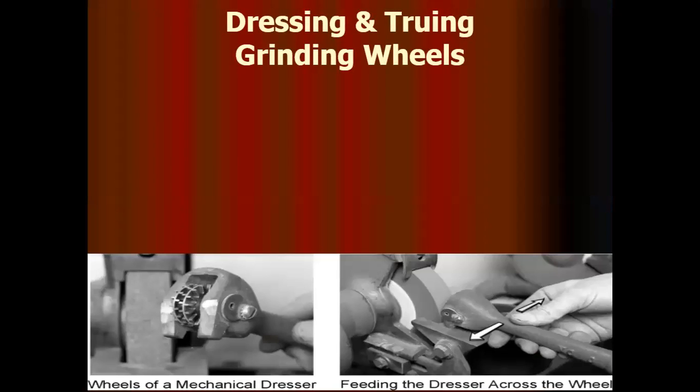Sometimes those wheels, they get a little out of true. Students will be grinding on one side or another, or jam a piece in and kind of creates a little chip in it. Hopefully that never happens. But what we have are these, they're called dressing tools. And you run this across the stone or the wheel, and it's going to help even out that surface.